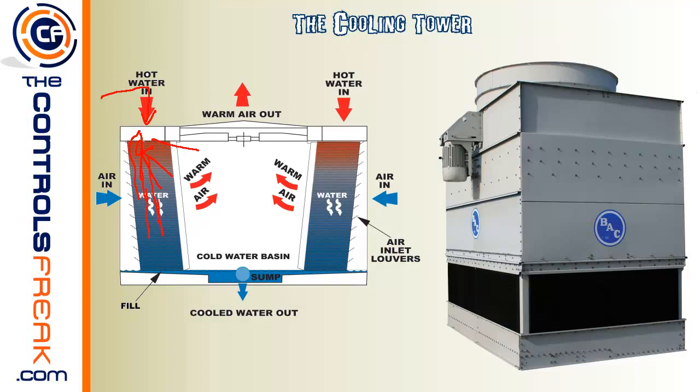Now raining down across just by itself would actually help cool the water down, with the air naturally coming, with the water pouring out and going across these little fins that are here. That'll actually give it a little bit of cooling. So sometimes you'll actually use that as a first stage of cooling.